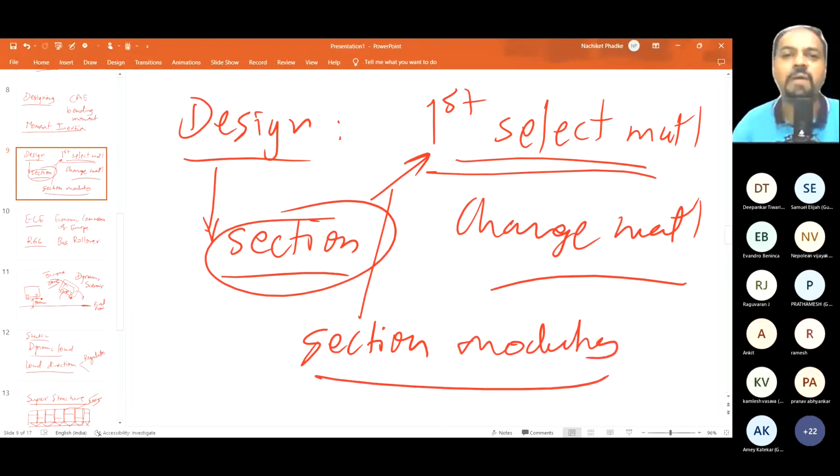Okay, typically we design section modulus because in tension the material itself is so stiff most of the time. But when it comes to a load where the load is a little far away from the support, there will be a moment created, and that moment is going to cause a bending scenario which is associated with the entire structure, and it's all going to collapse. This is something which is not being taken into account when we design a few important areas of a vehicle.